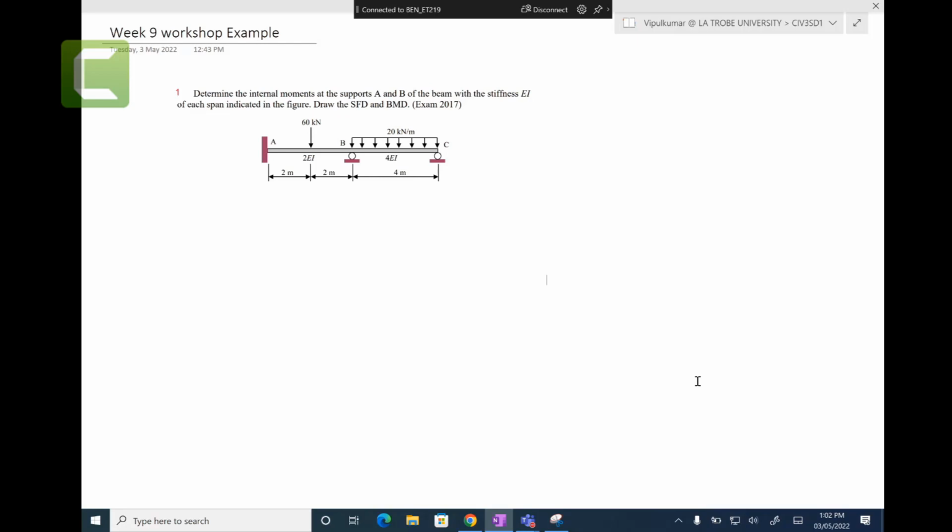Let's say you continue this beam with more rollers. Displacement methods are quite useful in that sense. Force methods will have some limitations. They can be useful when the degree of indeterminacy is 1 or 2, because then you will have simultaneous equations to solve. But displacement methods are quite powerful. These methods were invented in 1914. We still use them because they are very fundamental. They give you a sense of what is actually happening internally, and then you can build on those fundamentals.